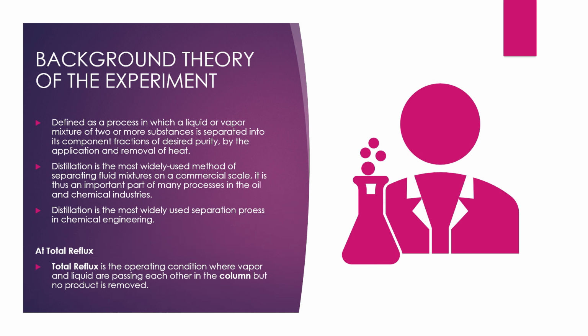It is thus an important part of many processes in the oil and chemical industries. Distillation is the most widely used separation process in chemical engineering. Total reflux is the operating condition where vapor and liquid are passing each other in the column but no product is removed.